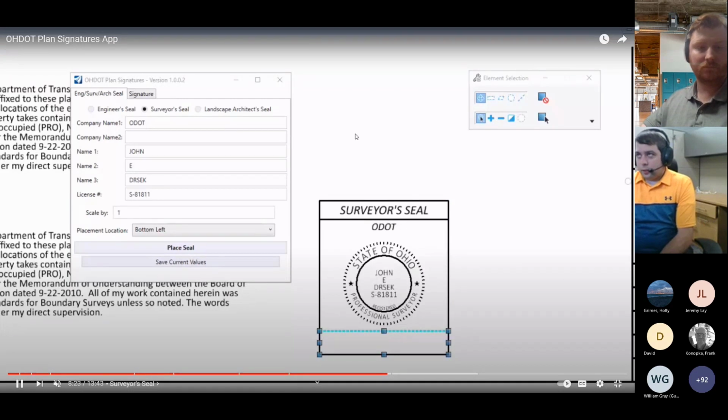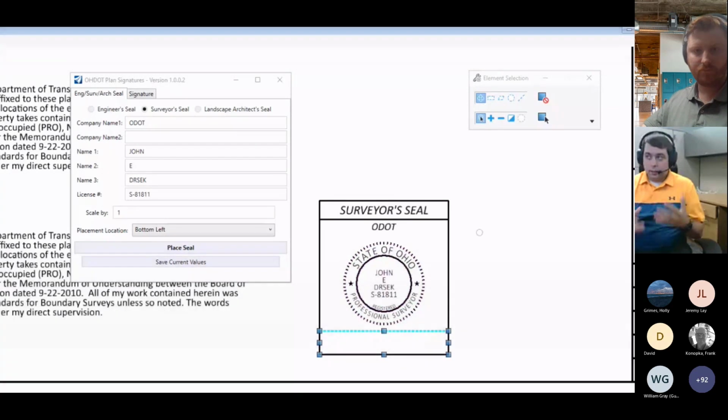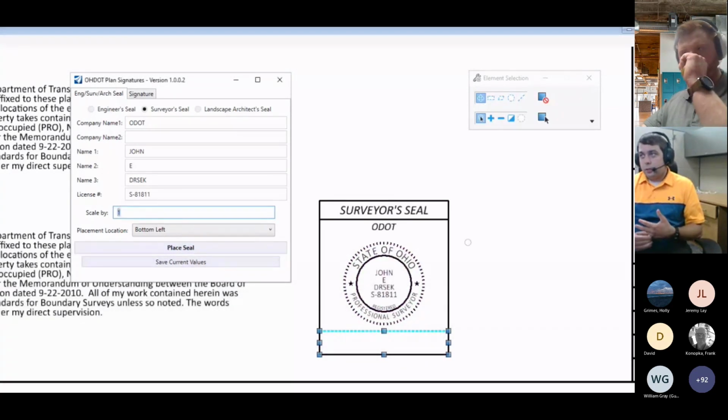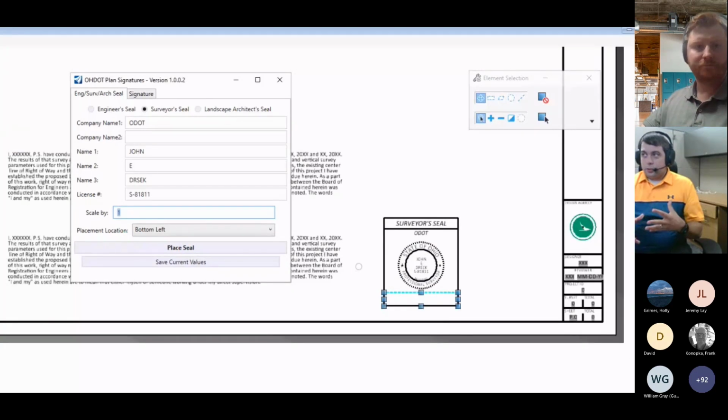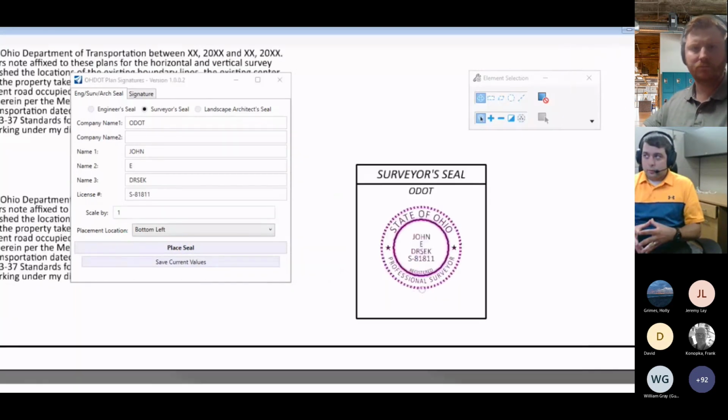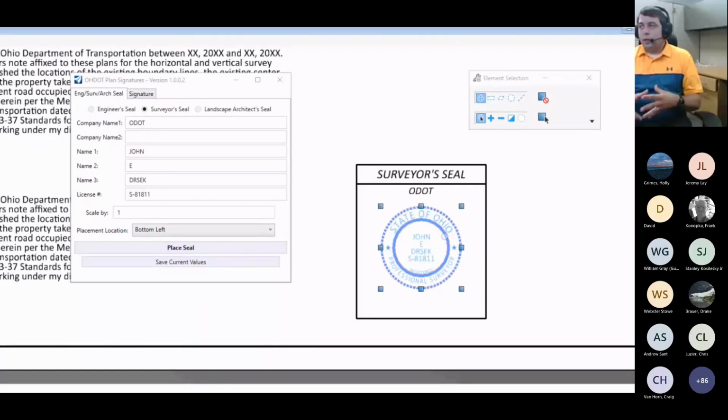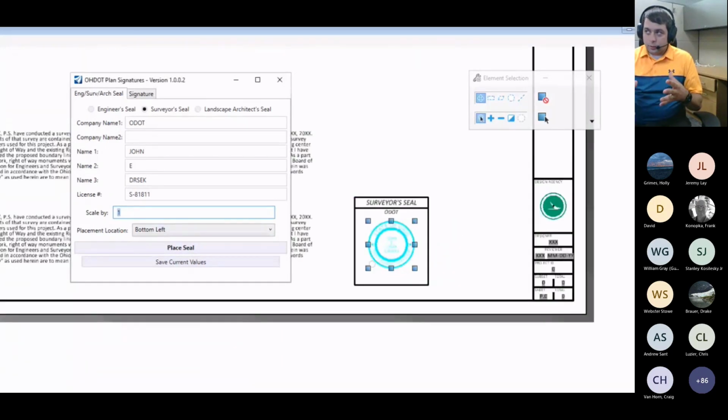So the other thing I wanted to call out with the right-of-way side, or I guess the surveyor side, is if you're going to have to, say, maybe hand sign this for the right-of-way plat sheet, you're gonna want to make sure that, depending on the county requirements, some of them are really strict, it's the exact right size. So the thing to remember here is that all of our sheet cells are set up with full size, so 22 by 34.